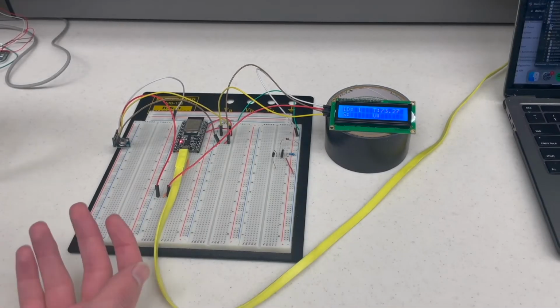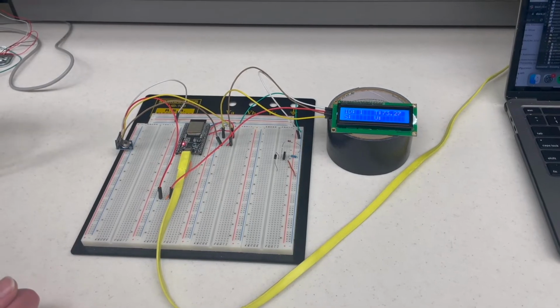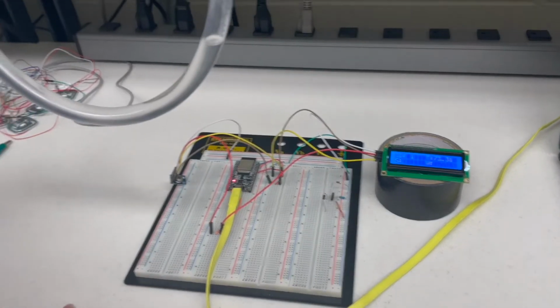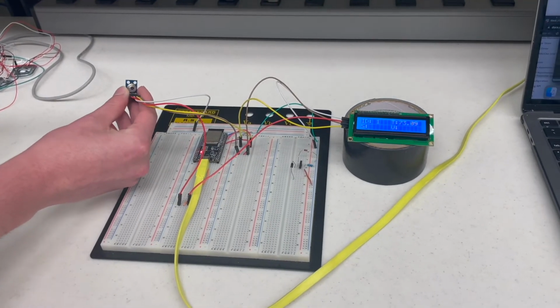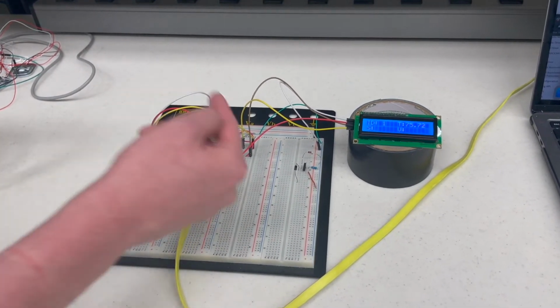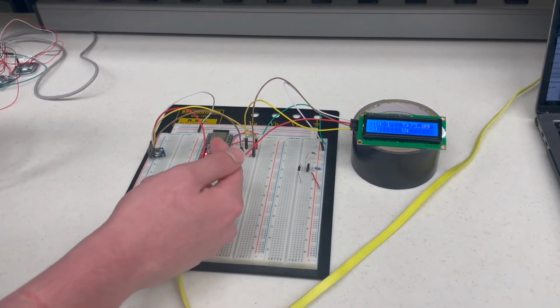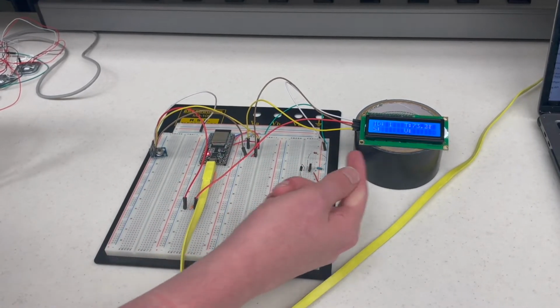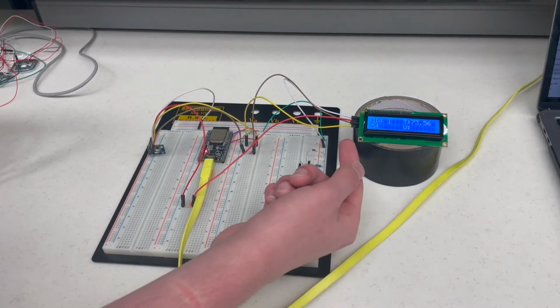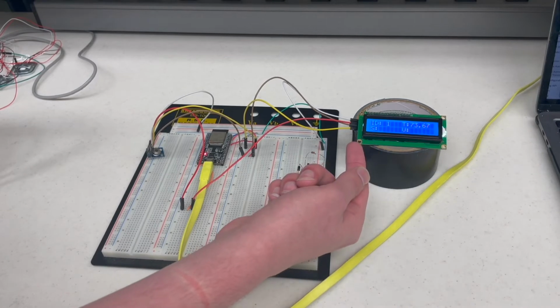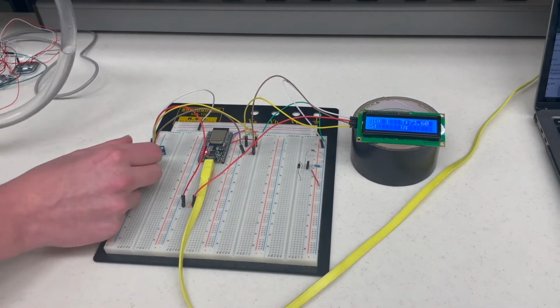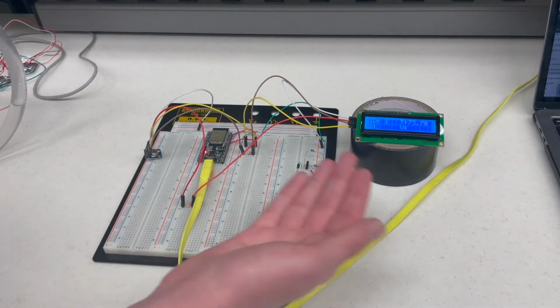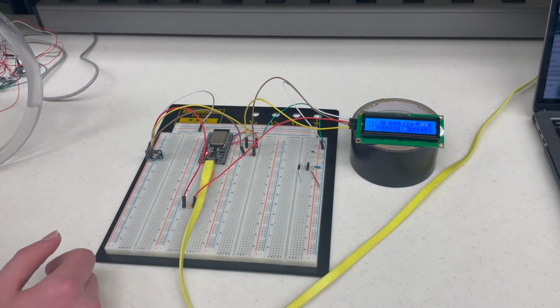All right, so here we got our test setup for the IR sensor and display. We got a tube filled with some cold tap water. On the left, we got our non-contact IR sensor. It goes to the MCU through I2C, and then it communicates to the display through I2C to update the temperature reading. There's also spaces for volume and the set dispense volume, but for the sake of the demo, we haven't implemented those yet. All right, to show the ambient temperature is reading about 73 degrees.